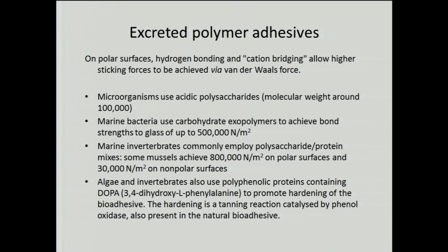The marine bacteria, which we said are the problem with ships, use carbohydrates which achieve a bond strength of up to 500,000 Newton per meter square. That is why I said it is so difficult to remove, and it is done by these bacteria putting in these carbohydrate exopolymers.